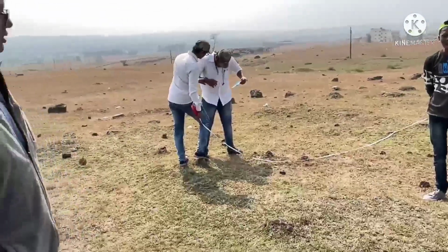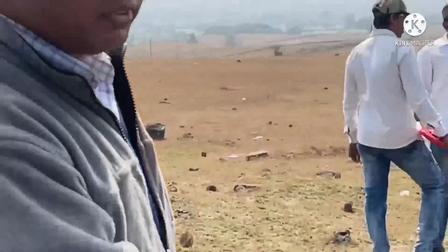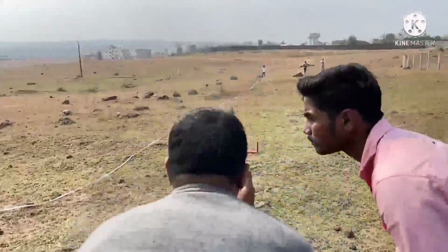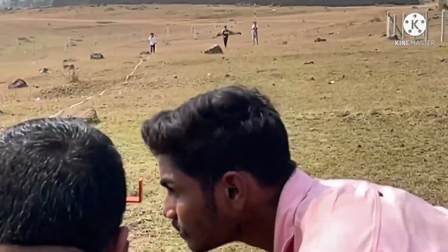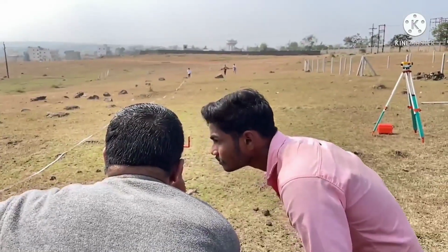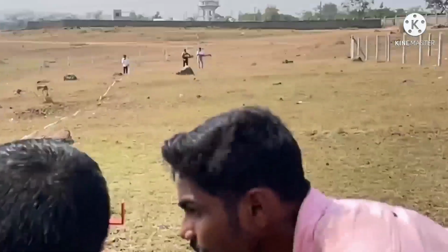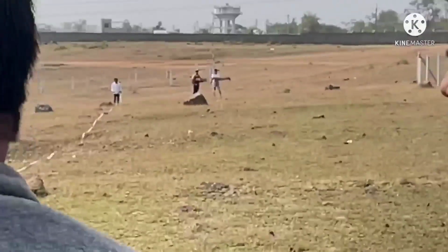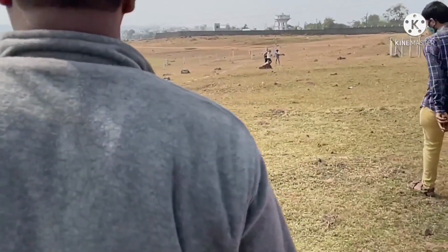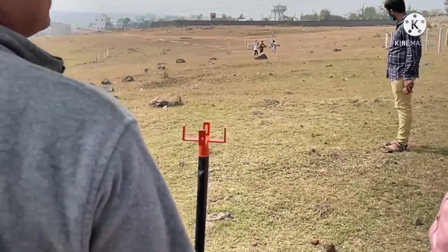So again now we are going to bisect the center ranging rod, that is C100, and the other person carrying the ranging rod will be standing on the right hand side. Okay, so here you can see the person is standing. Again giving the sign conventions to move in the left hand direction or in the right hand direction, correspondingly the person is moving. Okay, so now as it is having a perpendicular angle, that is 90 degrees with respect to the C100.